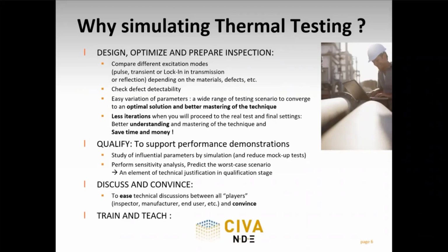So why simulate NDT? Why simulate thermal testing more particularly? Well, the idea is to provide a virtual prototyping tool, a virtual design tool, so that you can try, check, maybe make some mistakes, but virtually on the computer before going to the real test. And we hope it will help you to save money in the end. You can, for instance, compare different excitation modes and try different heating times, depending on the materials and the type of defects.